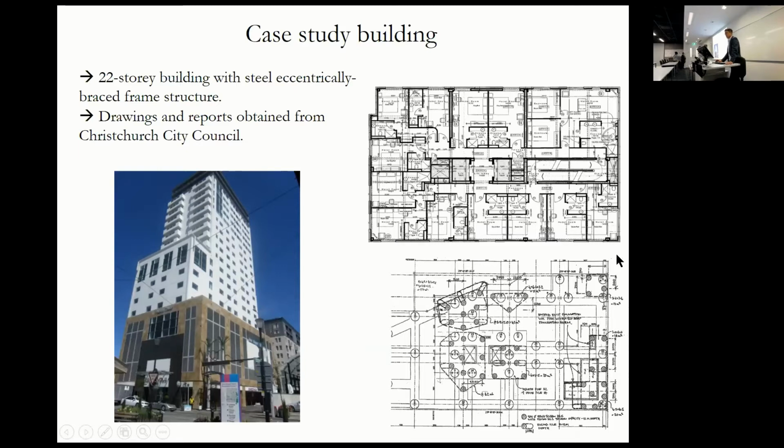So what you can see, a few interesting points to note is precast concrete cladding with perforated windows up the height. Quite extensive over these upper levels. Another interesting detail, if you look at the plan, it's a mixed-use building. So this is showing a residential type layout, which is over most of the building, say 2/3, and a lot of partition walls. And you've got eccentrically braced frames in around here, and you'll see the structural model we developed in a minute. Another thing you can see is a foundation plan and pile foundations, and we'll talk a little bit about that too.